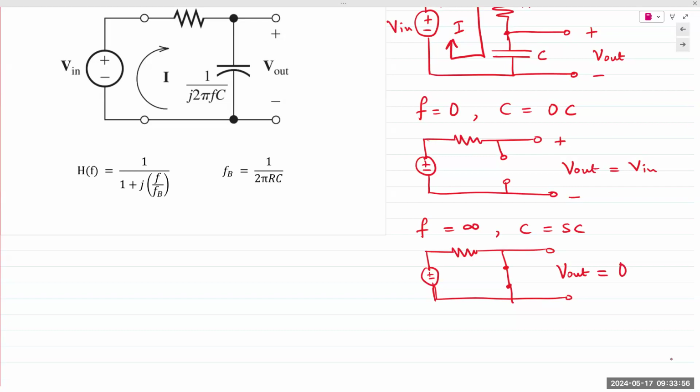Again, no mathematical or quantitative calculations required. This is what I call the handy dandy table. Use the handy dandy table, and you simply look at the circuit at 0 and at infinity and see V out, is it 0 or is it equal to V in? That's it. Output yes or output no. So in this case, we see that when frequencies are low, you obtain output. When frequencies are high, output is blocked.